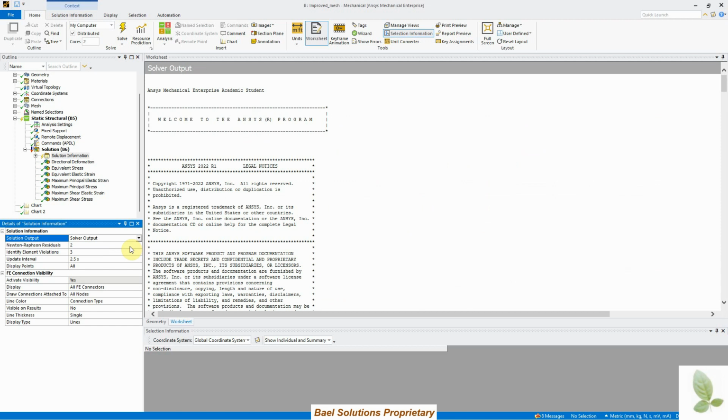Many nonlinear simulations involve large deformations and strains. This is frequently seen in hyperelastic, elastoplastic, or viscoplastic material simulations. In these simulations, elements are often strained so much that element shapes significantly change. Highly distorted elements cause problems in the FE model solution.